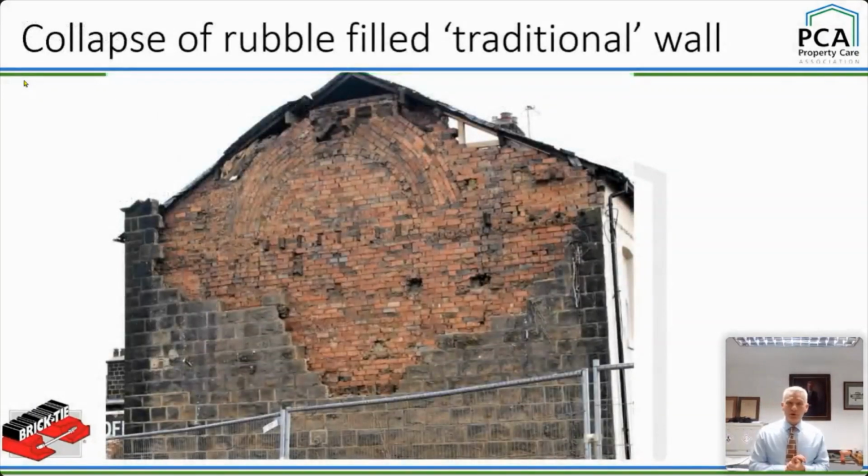So, first photograph. Again, I've used this before. I like this picture. It's a job that we did in Leeds quite a long time ago. But the thing about this is it illustrates how robust buildings are, because that's had a catastrophic collapse of the external leaf. It was a traditional wall, but it's caused by wind pulling on the wall. A sign was on it, and that amplified that. We can see the inner leaf, but the house is still occupied. The guy could still be in his bedroom having a Zoom meeting like the rest of us. Life goes on. And that's how robust houses are.